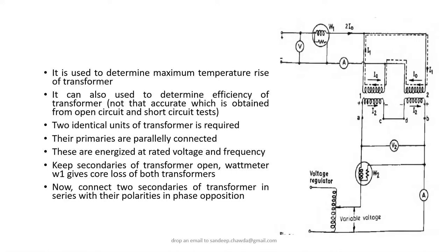I think if you try to recall, we have discussed the same thing earlier: without loading, you are in a position to measure the actual losses occurring in the transformer, that is iron losses and copper losses. You need not load there. Whatever actual losses there are, according to that you will get accurate efficiency.